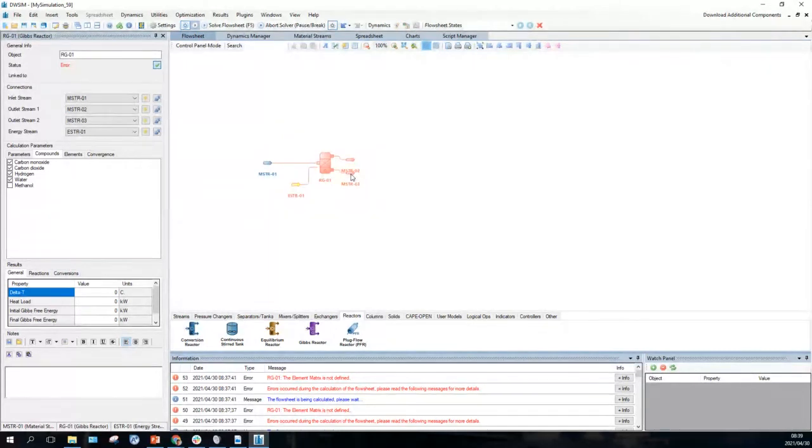So I wasn't so sure whether it was the NaCl itself or because I deleted the liquid streams. So I had to add in the liquid streams afterwards, and that's why you'll see that they've got naming. I've called them LSDR and VSDR on the next one, simply because I deleted them and I had to add them again.